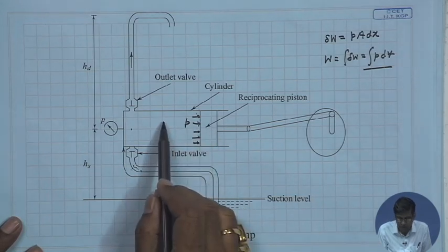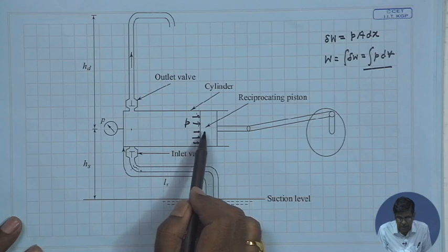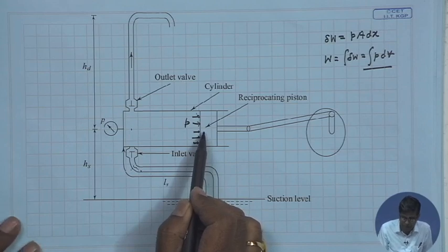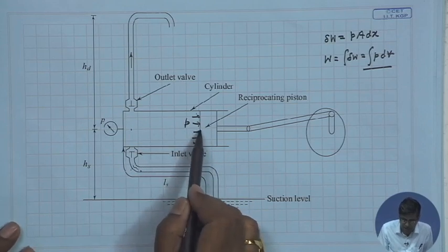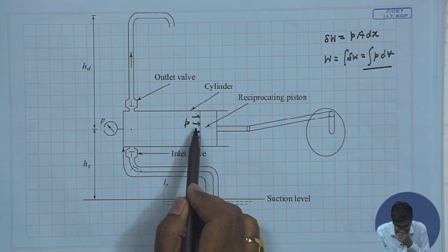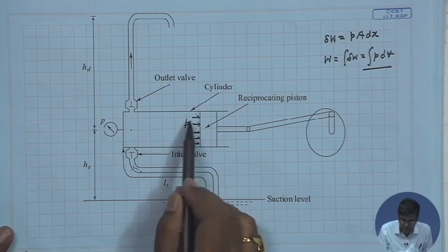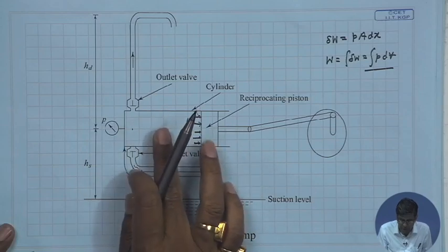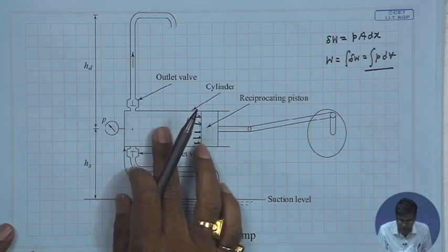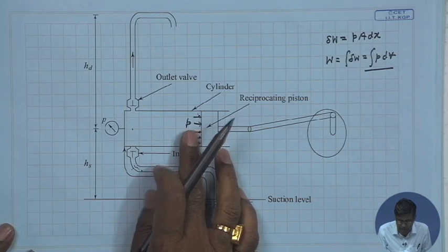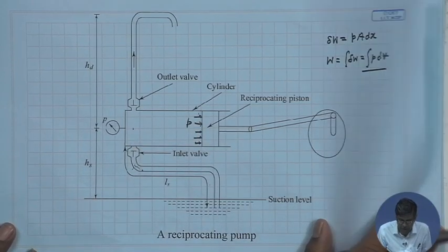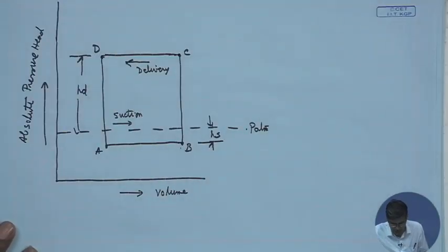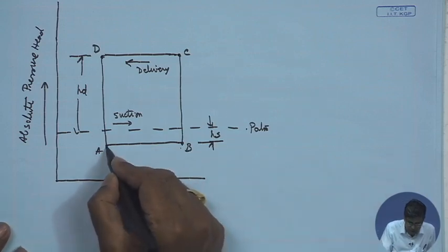That means velocity from a maximum value goes on decreasing and comes to zero, when again acceleration becomes maximum with a minus sign, that means deceleration. So, the rest part is deceleration, where a higher pressure is needed in the cylinder during the suction stroke. So, to take care of the initial acceleration and subsequently the deceleration, the head requirement in the suction stroke can be modified like this.